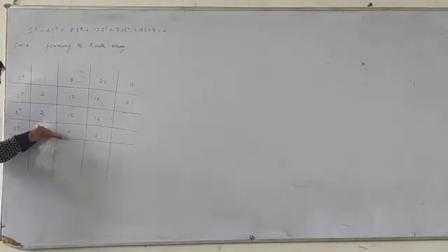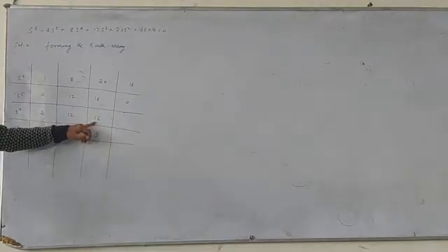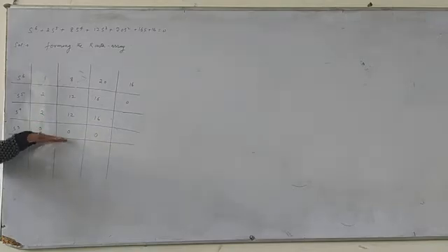Now what do we have to do? When this row becomes prematurely 0, you get 0, 0, 0. Now what do we have to consider? We have to consider the auxiliary equation, which will be from the row above this row, and we have to differentiate that auxiliary equation. Once we differentiate it, the coefficients of the differentiation have to replace these zeros. I'm going to repeat it again. We consider the auxiliary equation from the row above the row of 0, which will be 2s^4, 12s^2 and 16. We differentiate it, and whatever coefficients come, they have to be replaced here.